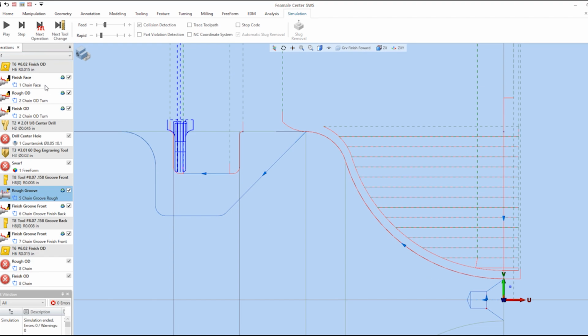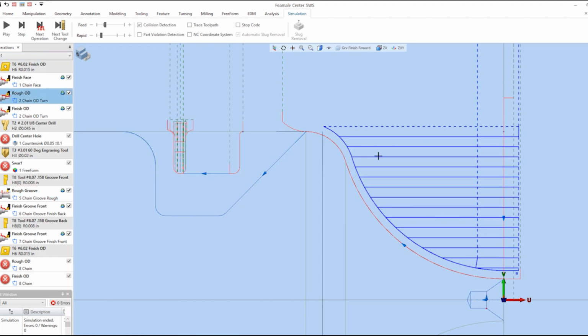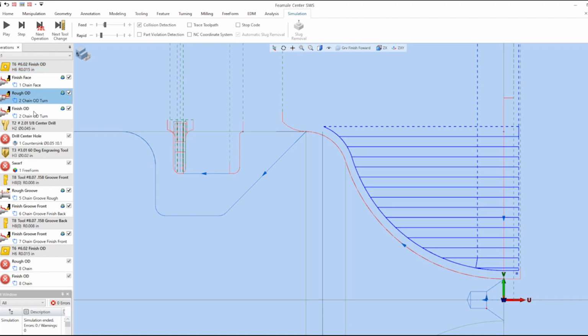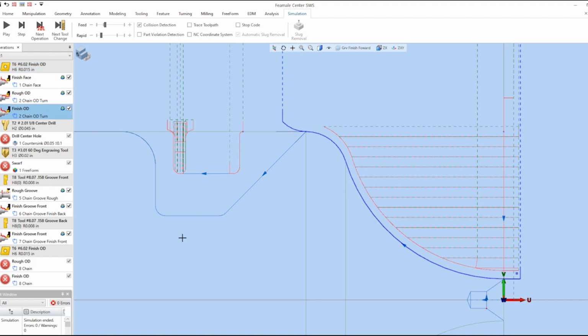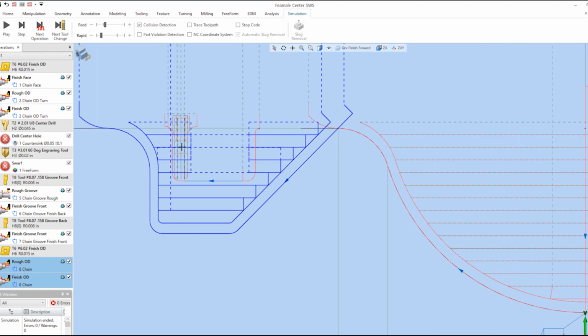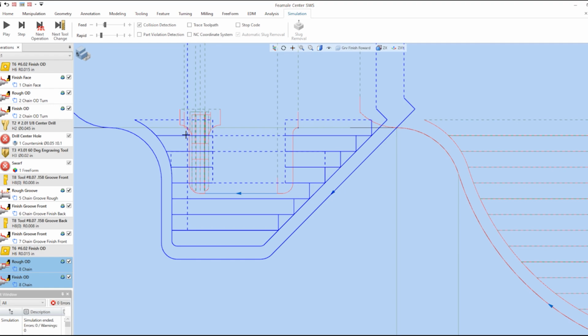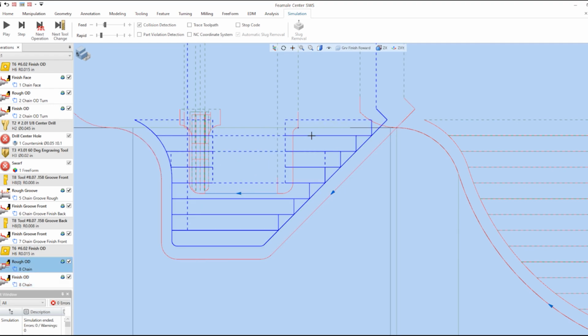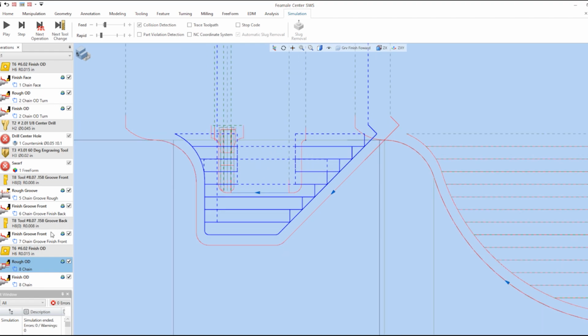And the only thing I'm really trying to impress upon you is to have your settings the same. And you can use tip comp, because that's what I'm doing here on these cycles with the CAM software as well. Notice how, because I've grooved out this groove, the CAM software knows that stock's removed by the grooving cycle. So the actual roughing cycle for this undercut takes that into account. It's kind of interesting, isn't it?